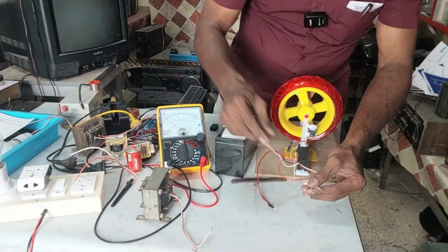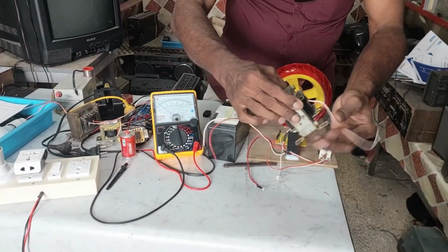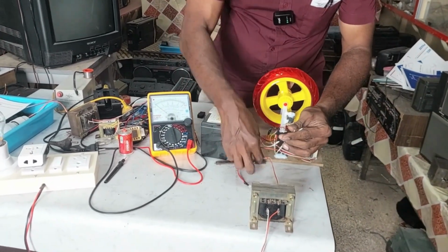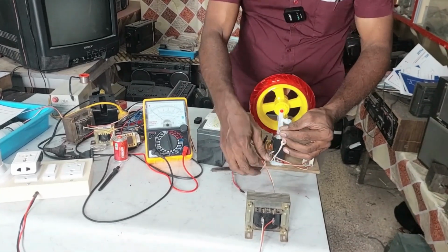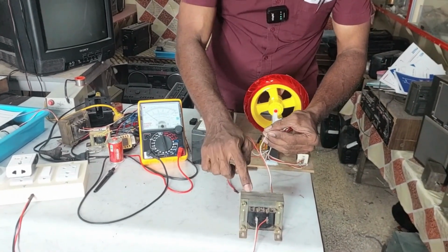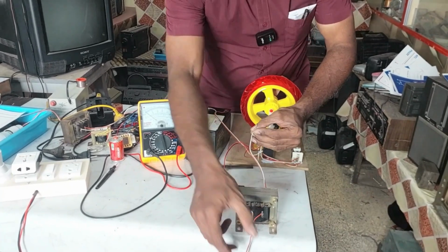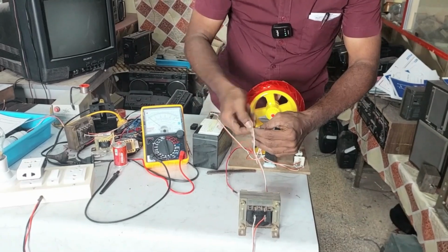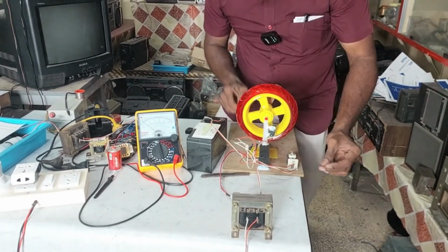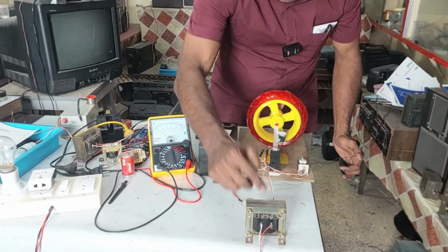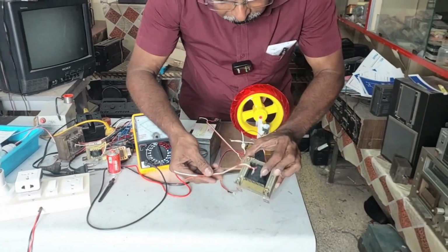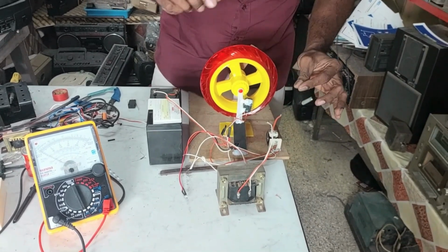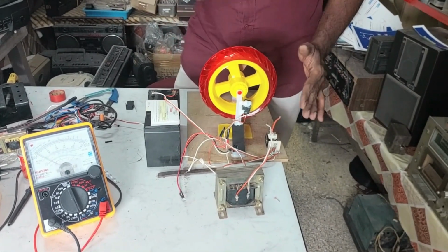Now, I am connecting this setup to the 12-volt side of a transformer. See, this setup cuts the DC and feeds it to the transformer. But to the transformer, it appears like AC. So, it steps up 12 volts to 230 volts AC. When this rotates, the DC voltage is chopped and supplied to the transformer. So, the output becomes 230 volts AC. This setup acts like an inverter.